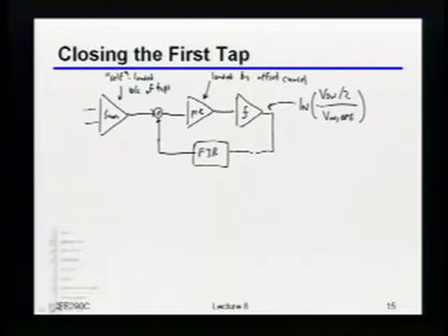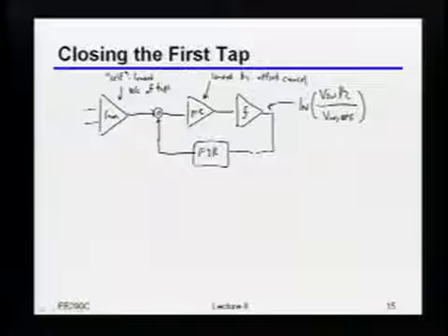So in other words, if I have some peak swing at the output, then whatever that peak swing is, I have to at least get, okay, nominally eventually I have to get it to full rail, but maybe from a digital delay standpoint I only have to go half of the way, right? But the amount of time it's going to take me to do that regeneration is going to be at least this. In other words, it's going to be just some minimum amount of time it takes you just to get that small signal back up to the large enough rails.